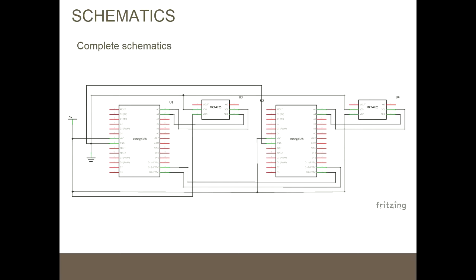Now, this is the schematic that I drew up. We're going to be using two Atmegas. Each one represents an axis. So in this case, one Atmega is going to be X and the other one is going to be Y, since the Lorenz Attractor is a three-dimensional equation. So each DAC with its Atmega is going to compute one of the axes, while the other one computes the other axis. For my case, I just programmed them to run the same code. The only difference is one is for X, one's for Y. You can pick YZ, ZY, any combination that you want. It's not possible for the oscilloscope to graph 3 dimensions. I'm not aware of any oscilloscope that can do 3, but for whatever I was provided, I can only graph 2 axes, which was sufficient to produce a very cool-looking graph.